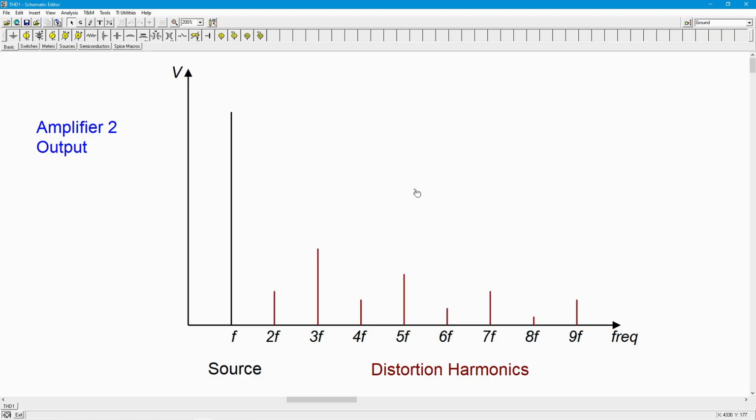And earlier I referred to, you have to be careful about the frequency that you're using for the test. What does it mean to talk about total harmonic distortion when your test frequency is above 10 kilohertz? Think about that for a sec. Where are your harmonics going to be?